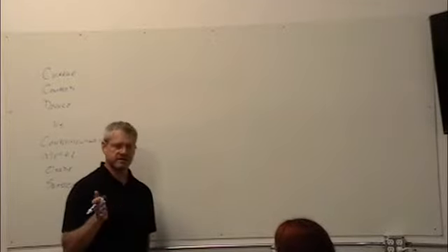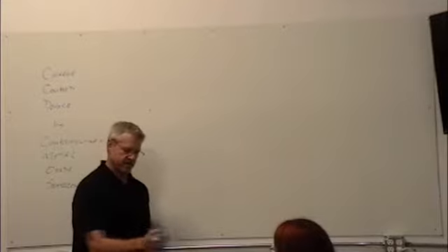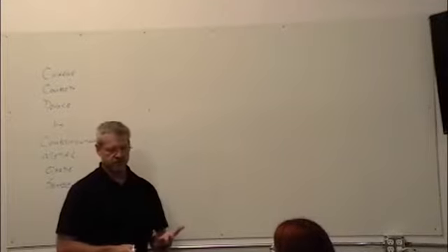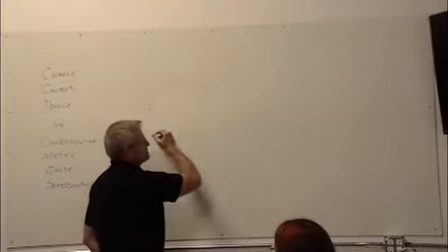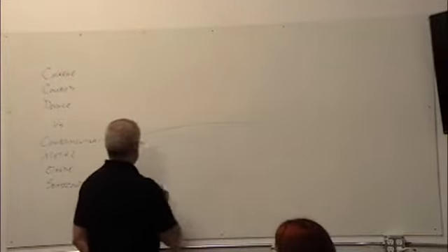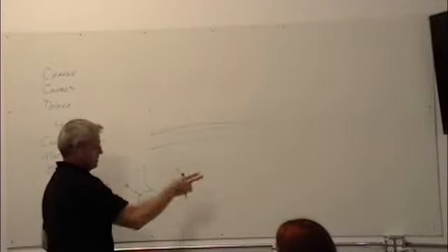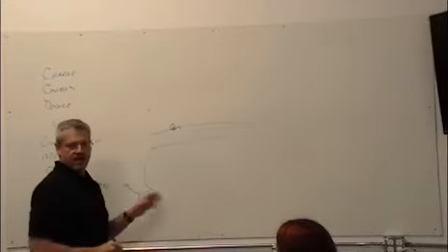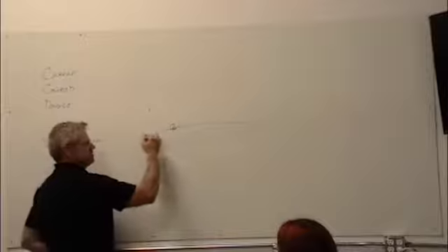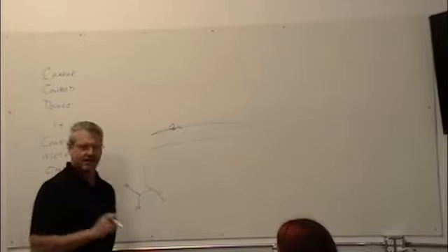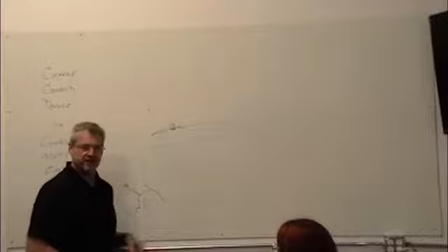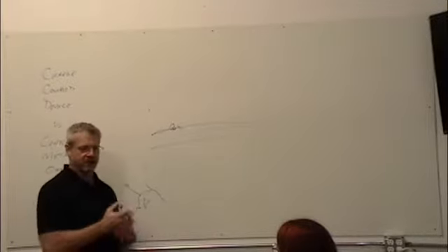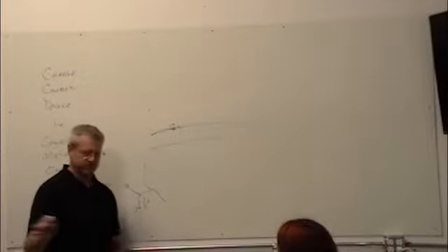which is a lot like a CRT, where you scan an electron beam back and forth across, but they're doing the reverse. As they scan the beam across, off over here sort of a ground, they're measuring the current that's coming back off. You say, oh, okay, nothing. You know where this is in time as you're scanning the beam. Well, if there's light falling on it from the outside, this phosphor gets excited, and now when the beam comes across there, it recharges that, and you get a dip in your current over here, and you know, oh, that was a dark spot there, and you know how dark it was by how much current it was. Everything's this precision timing thing.